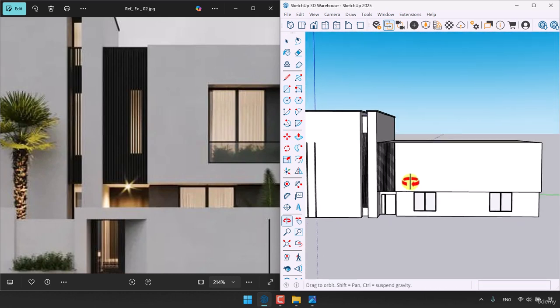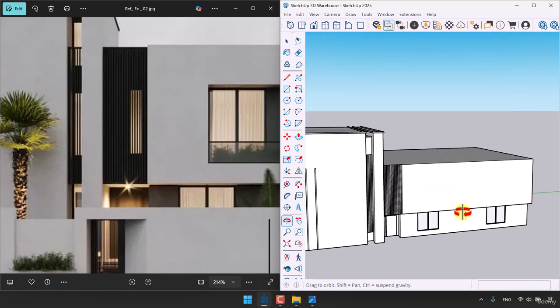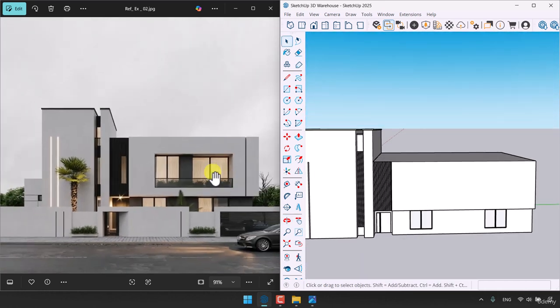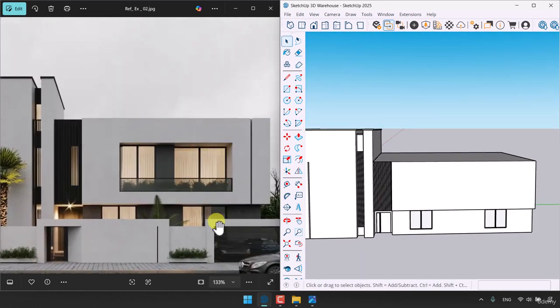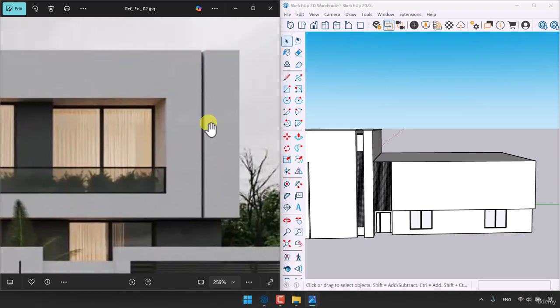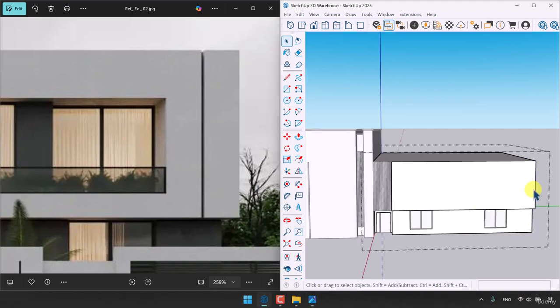Press Ctrl S on my keyboard. Everything is saved for me. So only this place is left for us. So I'm going to start with this line in here, the chamfer which is exactly extruded on the concrete panel. So I'm going to click on this line, click on the move, copy activated, and now I'm going to type 2.